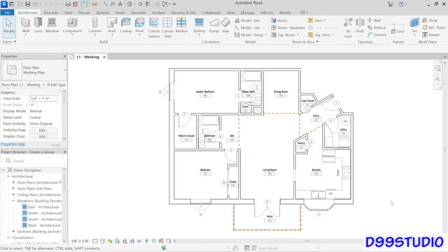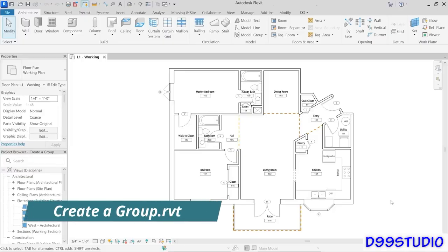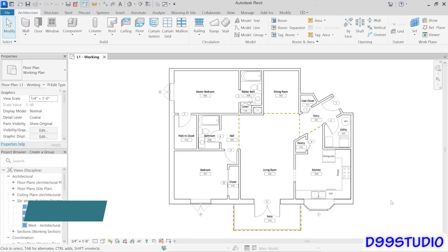Architectural design frequently makes use of repetitive elements. And when you have such elements in Revit, you can use a tool called groups to help you manage them. So to demonstrate, I'm going to be working with this 2-bedroom apartment unit layout here. And what I want to do is group it so that we can make multiple copies of it. And the advantage of grouping something first is that if you then come back and make a modification to one of the instances of that group, that modification will apply to all instances. So it just becomes a very useful way for you to manage those repetitive design elements.